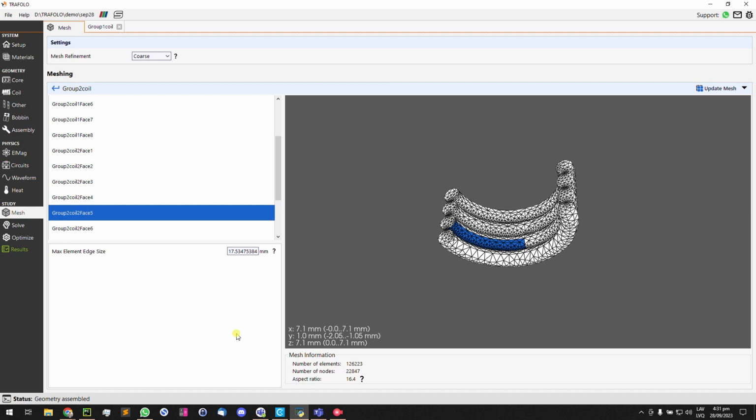And those who have used FEM simulation software should know how important it is to have an efficient mesh, especially for 3D, because 3D simulations are computationally expensive and you would aim for a smaller number of elements. Those elements should have a good aspect ratio, and the refinement should be put in those places that have the highest gradients.